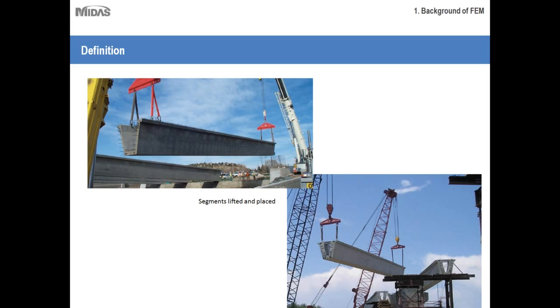In some cases, at some sites, there have been tragic accidents where the cranes have failed to lift a section because they were not properly supported at correct intervals. So you have to be a little more accurate, a little more cautious when you are dealing with these types of bridges and lifting them.